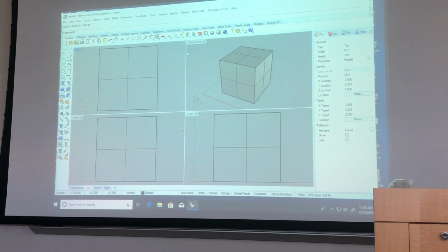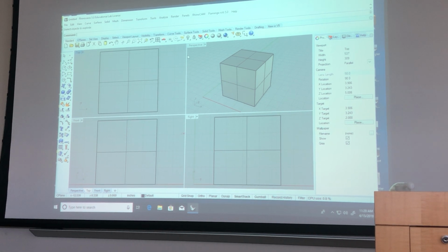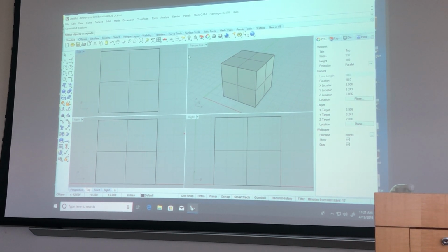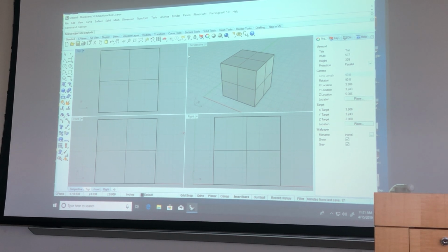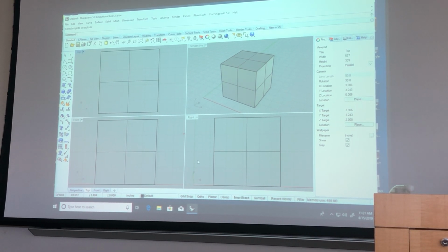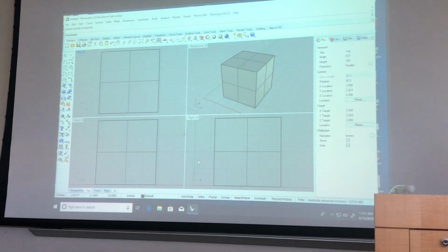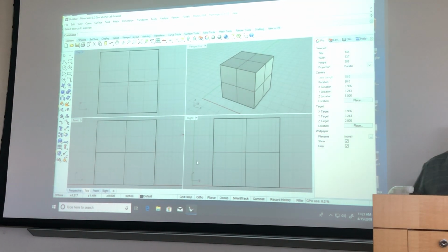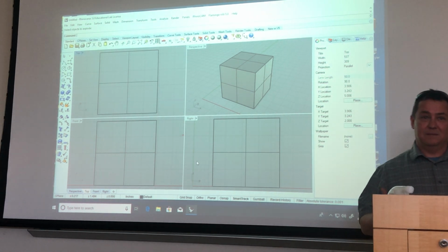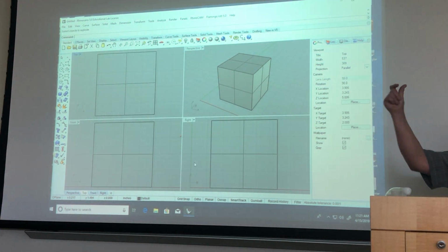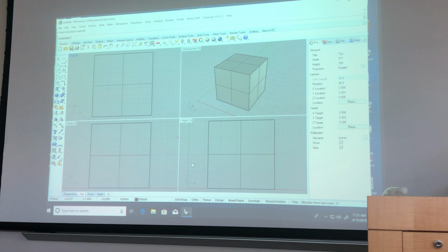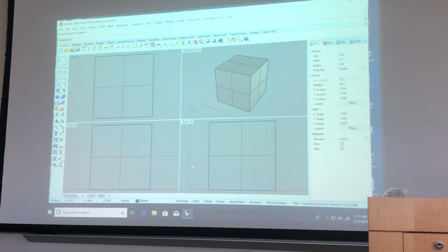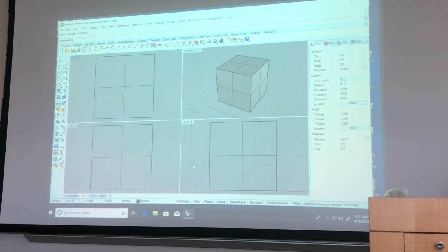Here's how Rhino will confuse you. You ready? I'm not doing anything, right? I'm gonna hit enter, and it launched the explode command again. If you right click, it will do the same thing. While you're not in a command, right clicking or hitting enter are the same thing, and they bring back the last thing you were doing. So hey, drawing lines, end a line, you want to start another line, just hit enter to start another line, or right click to start another line.